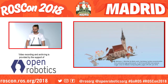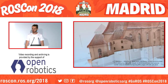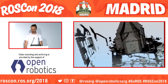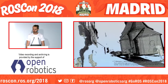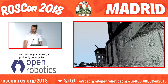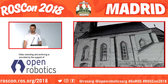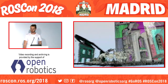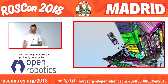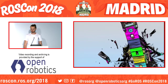So coming from a high resolution point cloud, or many point clouds registered to each other, we can reconstruct these using, for example, the Las Vegas Reconstruction Toolkit, namely LVR, using the marching cubes approach, and then reconstruct it to a mesh as we see in the video, and then also retessellate the triangles to reduce the data, and later also apply some textures to keep the color information, as we will see now.